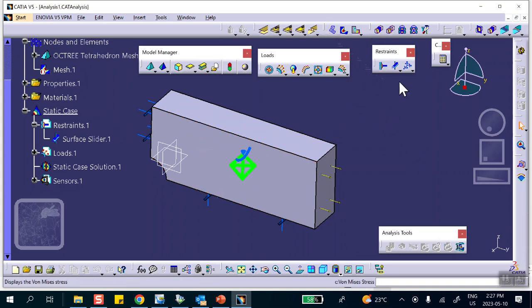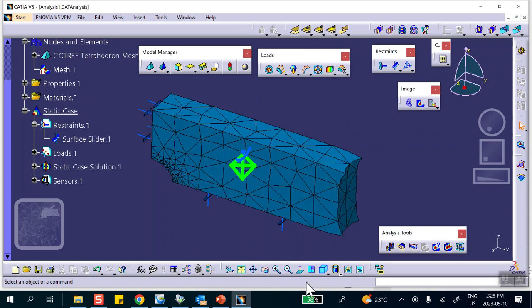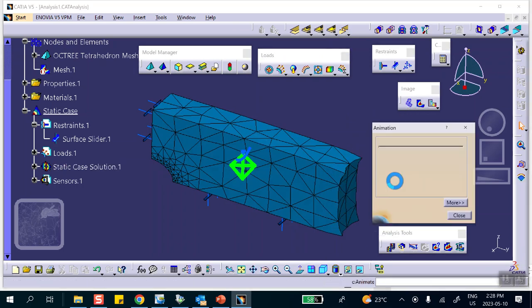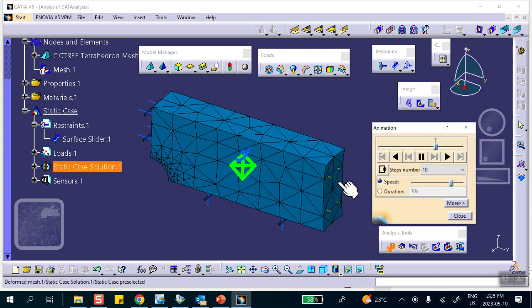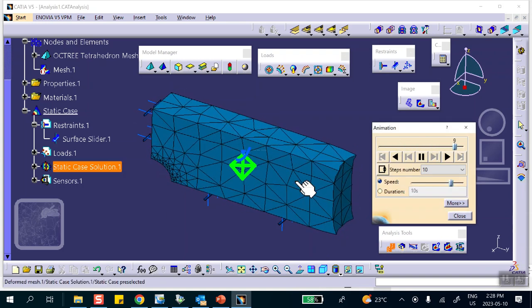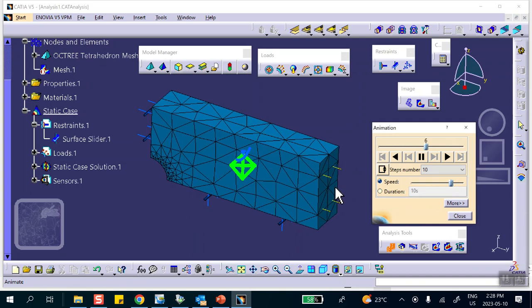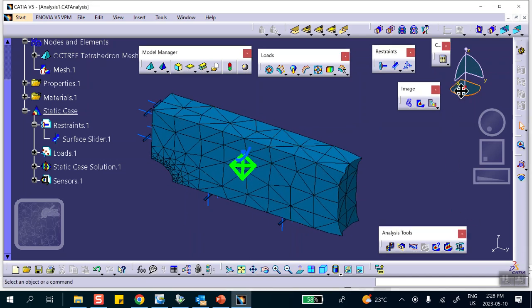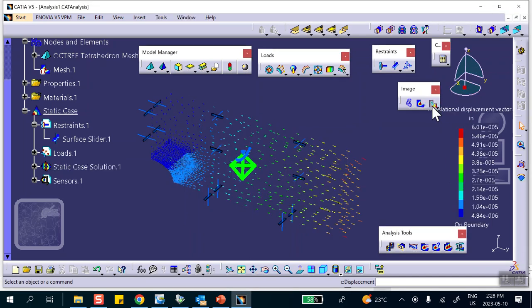Deformation is right here. This is the post-processing. Remember, restrain, load, compute, image. Okay? First deformation, just show me the shape without any numbers. Okay, that looks good. Because you take that piece and apply force to this end, and these are on roller, this just stretches. Now, if you want to look at numbers, you click on that.